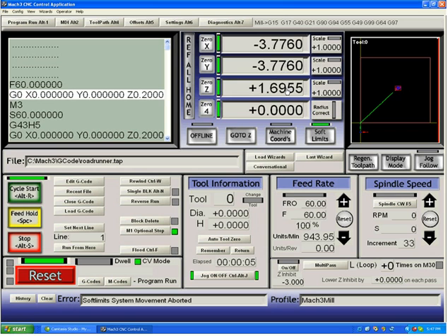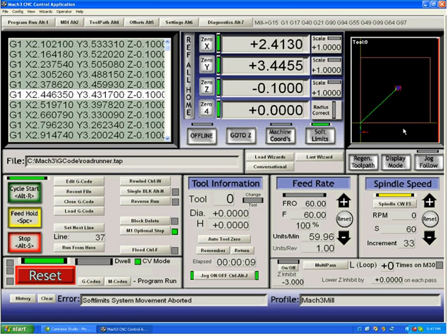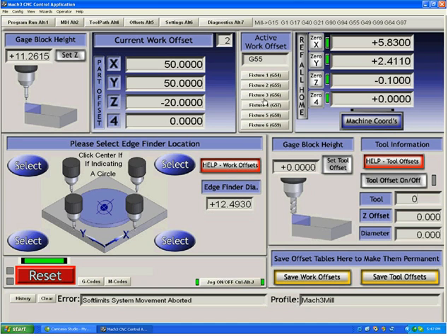As you can see, the Z is now moving down to get to the top of the material, and now the job cuts normally, even though it started from the home switch. So that's what an offset system is handy for. You can program different fixtures on your table which hold material, program them for the absolute coordinates. The only rule to remember is, once selecting offsets 2 and onward, do not push the 0 button or you invalidate those offsets, because pressing the 0 button changes whichever fixture offset is in effect.